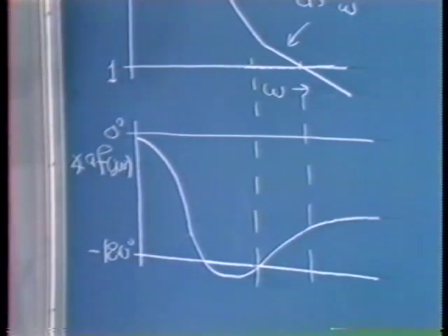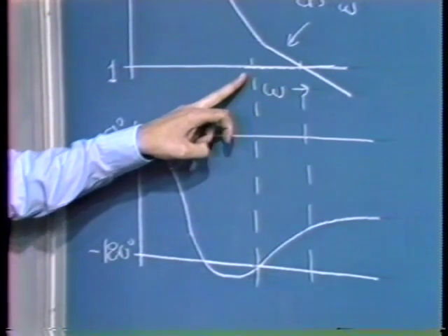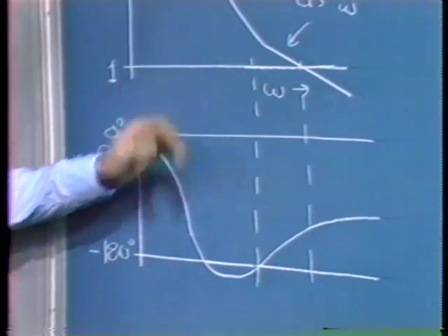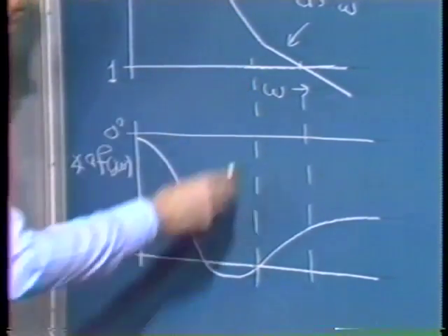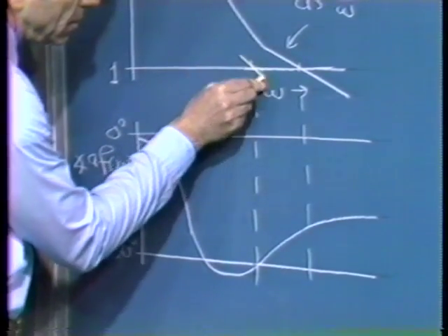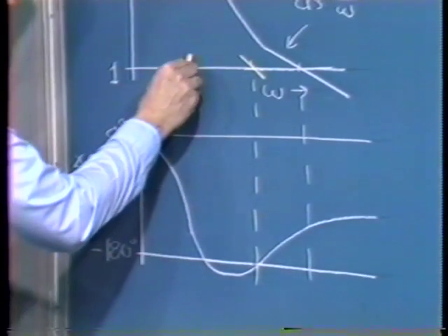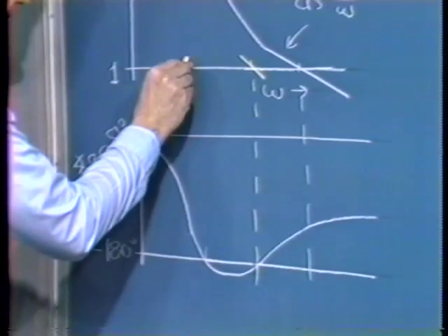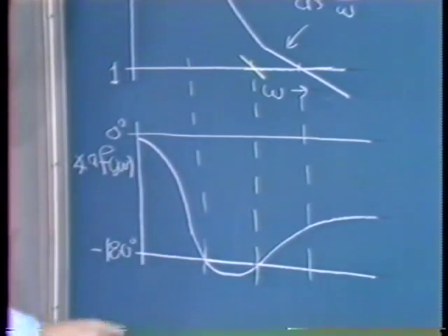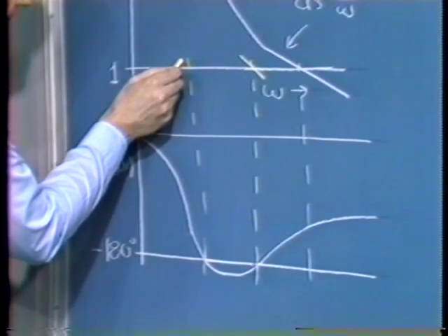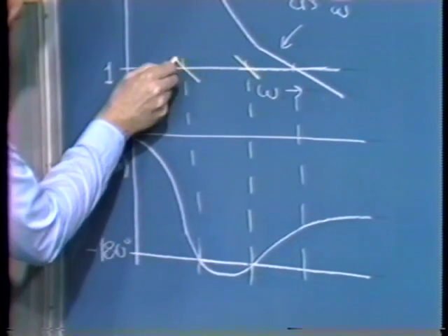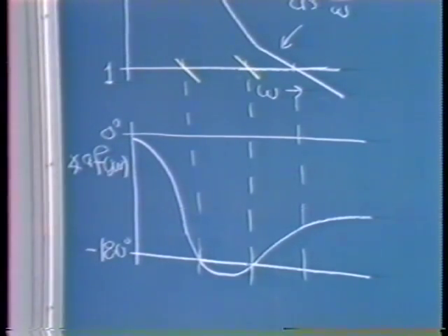In other words, if we drove the system in some way so that the amplitude at the input to the nonlinearity, the quantity E in our describing function analysis, had an appropriate value, we could force crossover here at a position of 0 phase margin. Similarly, if we had an even larger amplitude applied to the nonlinearity in our overall loop, we could force crossover to this frequency, once again, a frequency with 0 phase margin. So in that case, in the vicinity of crossover, we might have a magnitude versus frequency characteristic that looks something like so.